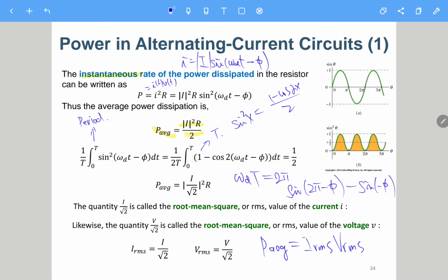So when we do something like a measurement or calculate something, you need to care about the root mean square value, just like what we have done in the lab for the magnetic induction. Some values are root mean square values. So you need to be careful about the factor of square root of 2. Otherwise, it will be a 30% error, something like that.